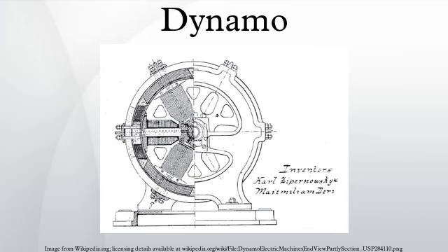Rotary converters. After dynamos and motors were found to allow easy conversion back and forth between mechanical or electrical power, they were combined in devices called rotary converters, rotating machines whose purpose was not to provide mechanical power to loads but to convert one type of electric current into another, for example DC into AC. They were multi-field single-rotor devices with two or more sets of rotating contacts, one to provide power to one set of armature windings to turn the device, and one or more attached to other windings to produce the output current.